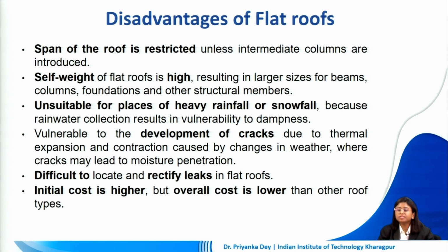It is vulnerable to the development of cracks due to thermal expansion and contraction due to seasonal changes, and these cracks will then open up vulnerability towards moisture penetration. So that is one major problem which is associated with flat roofs. Definitely, while making flat roofs, we have to accommodate this thermal expansion and contraction seasonally in the design of the structure. It is very difficult to locate and rectify leaks in a flat roof over time.